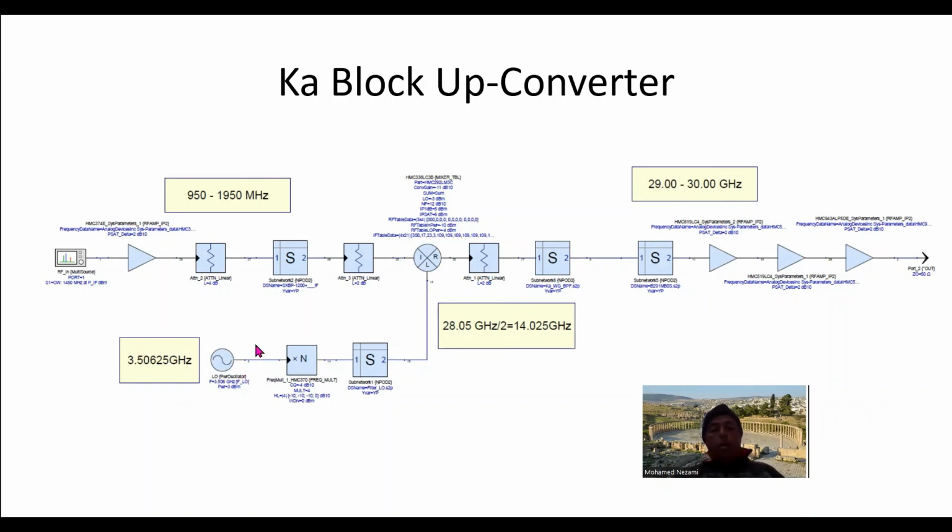It is out of the scope to talk about designing these phase lock loops, but you could utilize these phase lock loops from various sources. You could either build it from discrete components, the ones from TI, Texas Instruments, or from Analog Devices, or you could buy it as a module, a surface mount module from various phase lock loop hybrid circuit makers.